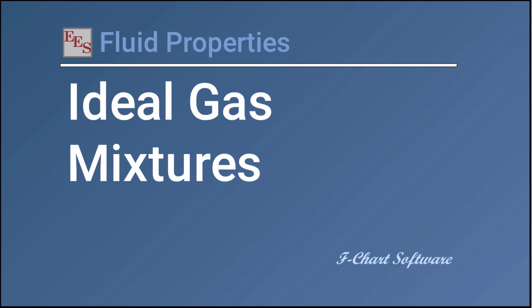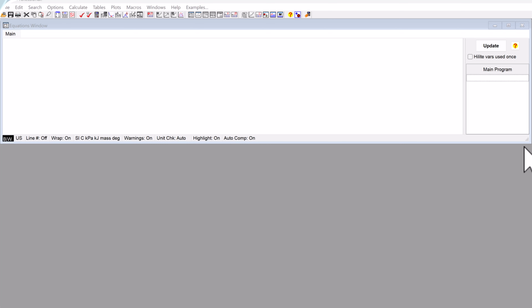So a new feature of EES is that it will allow you to define a substance that is an ideal gas mixture and then use that ideal gas mixture that you've defined in any of the built-in heat transfer or component library procedures that already exist. So in order to define an ideal gas mixture, you need to use a directive.